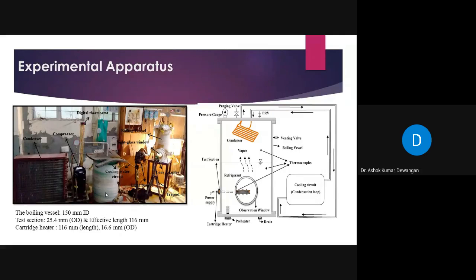Here I use this K-type thermocouple. Is there any difference between K type or T type if you use T type here? Yeah, there are many differences, because there is a difference in the temperature. One is the temperature, another is the temperature range, another is the sensitivity.